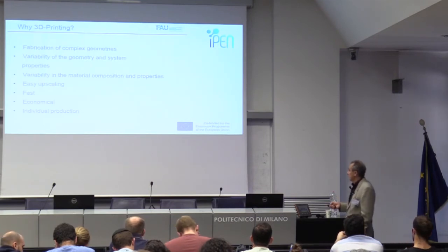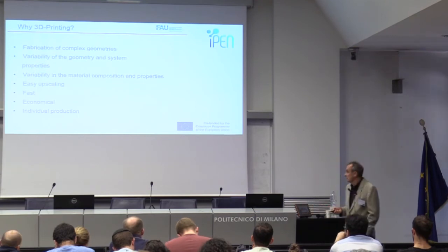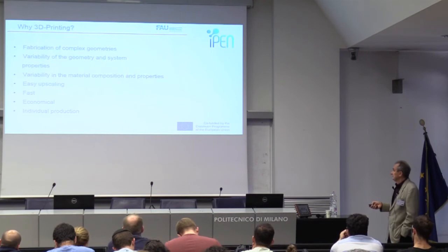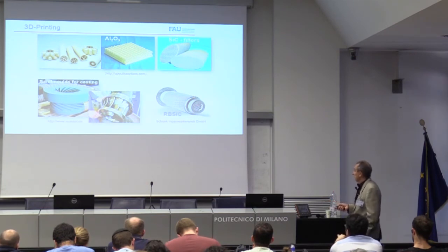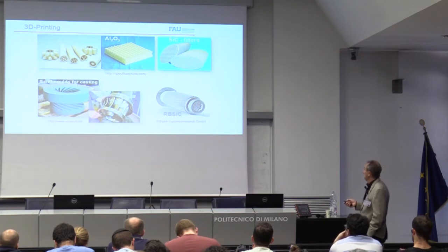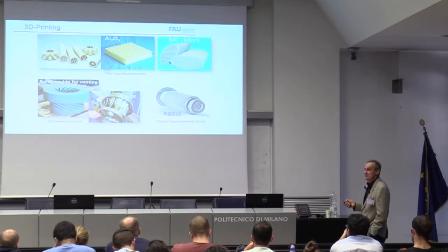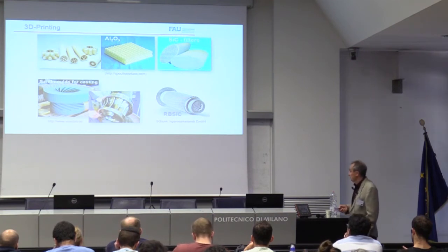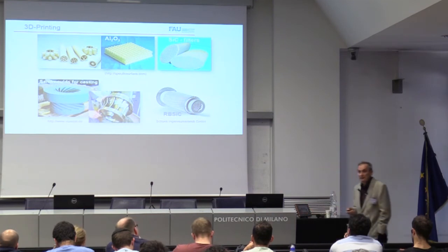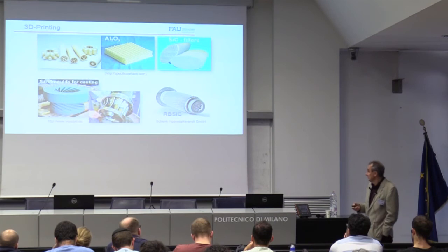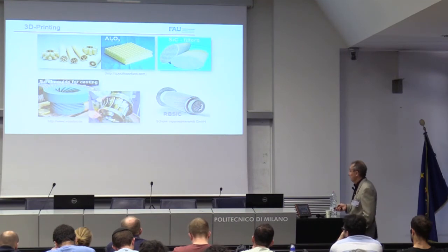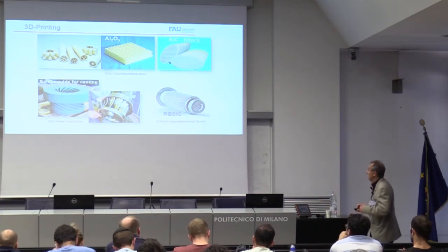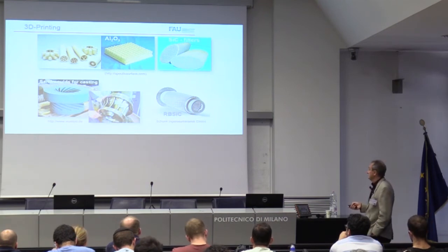But the reason for 3D printing is exactly the same as for additive manufacturing: samples which you can make in actually each form. And look, you can work also with silicon carbide. Silicon carbide is not easy to work with because the system has a very high melting temperature. But I didn't propose to make melting. It's enough to make temperature treating after printing. And of course, you can maybe use some flux material between grains and so on, to make your strong and mechanically stable system.